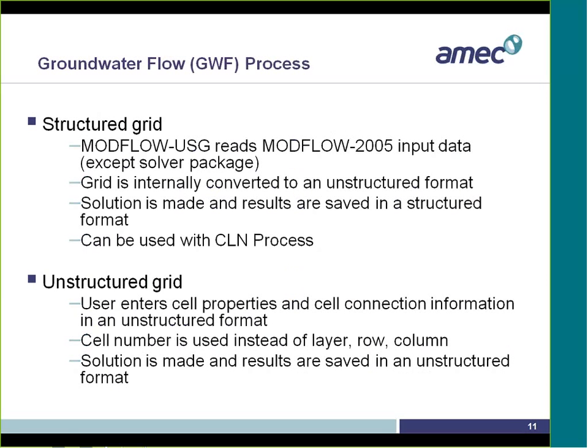The groundwater flow process. As I mentioned, you can use a structured grid for groundwater flow. It is fully backward compatible with MODFLOW 2005, except for the solver package. As I mentioned before, the solvers cannot be backward compatible because we have a new solver package for unstructured systems. The grid is internally converted into an unstructured format. The solution is made and results are saved back in a structured format.